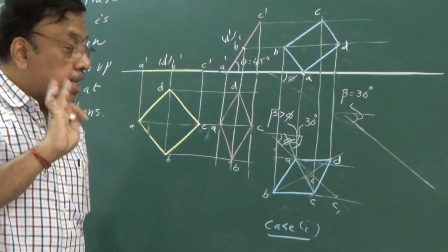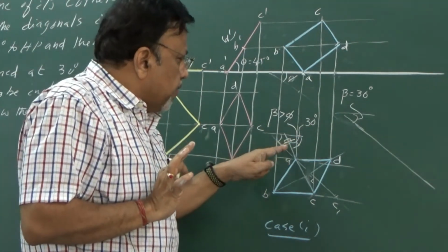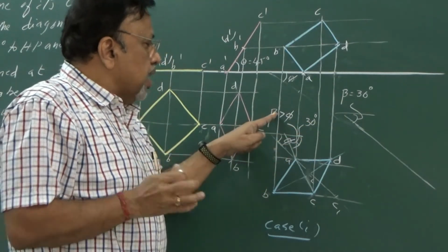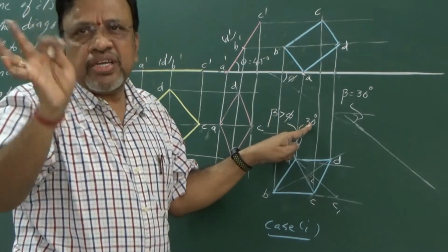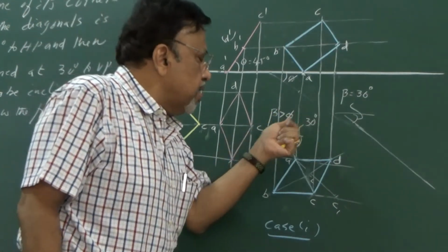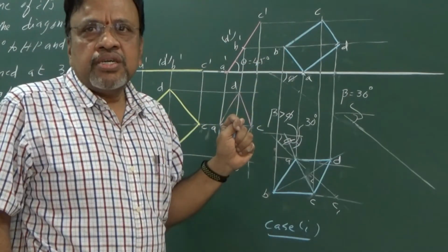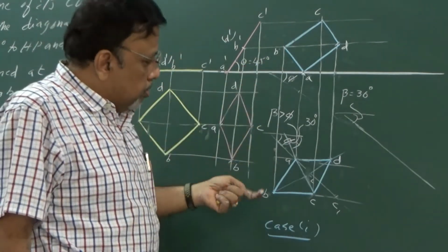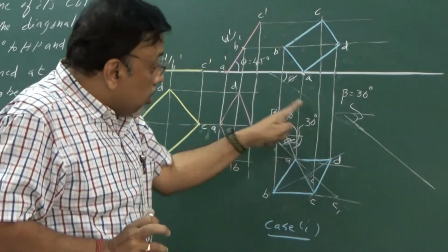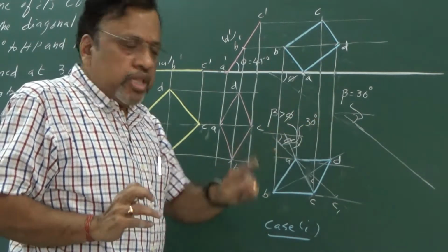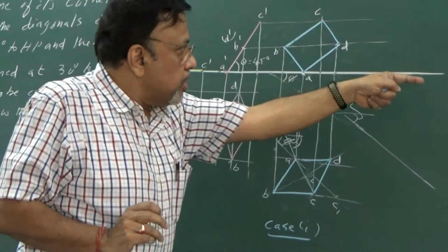So you can just see the difference between this. Even though I said phi is 30, if you determine beta, it will be maybe around 2 degrees or 3 degrees more. Let us say it is 30, it cannot be 45 degrees. Maybe we will get another 2 or 3, maybe it will be 33 or 32, something like that. So obviously your shape will not change. But you should not say that sir, shape will not change. Whenever you do this particular shape, we are going to look for whether you have calculated the apparent angle. Once you have done this, we are going to give the full marks for this stage.